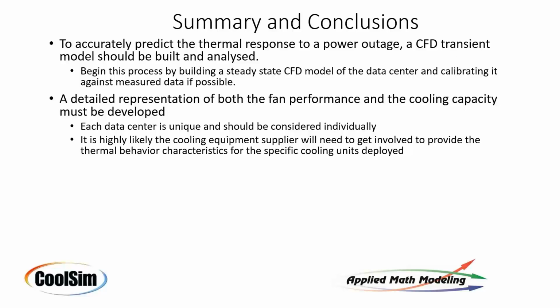Each of these situations is unique, and the cooling systems are all a little different. For example, some of the evaporative cooling systems are better at this kind of response than the traditional compressor-based systems because the reset time is quicker. If it's evaporative, it's going to evaporate. It's going to continue to work even though you may have gone through a power spike. Unlike the compressor-based systems, which often have to go through a full reset and make sure that the flows are correct so that you don't freeze a coil and damage the equipment. So the startup on a compressor-based system, whether it's a DX or a chiller or some other type of system, generally takes a little bit longer because they're bringing it up in a sequential fashion to ensure they don't damage the equipment.